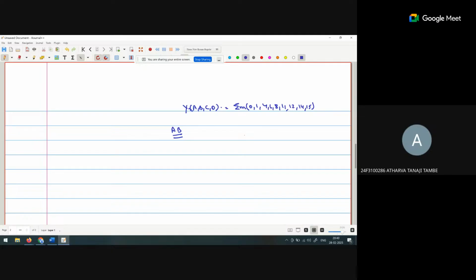Sir, it's our choice to select the select lines. We should not use that formula of log to the base 2, what you are saying? Like for the select lines, we were using the formula of log to the base 2. And for the three variable case, you selected two lines and one input, no? So it is in our hand that we can use that as a 4 by 1 multiplexer or 2 by 1 multiplexer.